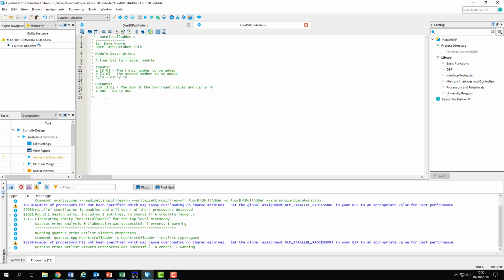As before, we construct the module's outline and declare the ports. Note that I'm using the same identifiers here as I have done in the single-bit adder module. This is perfectly okay practice, as there is no danger of redefining the scope of a variable in Verilog hierarchy, unlike in sequential programming languages where you have to deal with local and global variables within a single file.